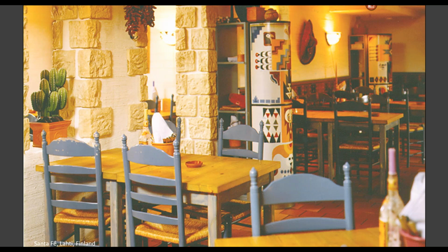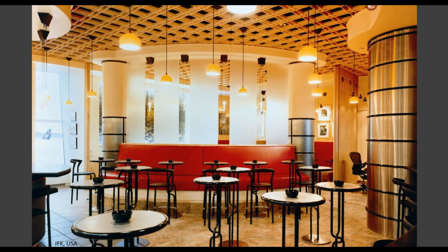Here we have a smoking room, and this was in JFK Airport. I don't know if this is actually still there since smoking rooms are becoming, going the way of the dodo. But smoking room was the perfect application for displacement because again, we have lightweight contaminants, the smoke, that we want to remove from the occupied space up towards the ceiling. And what better way to do that than with displacement?